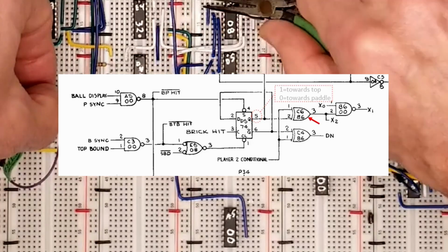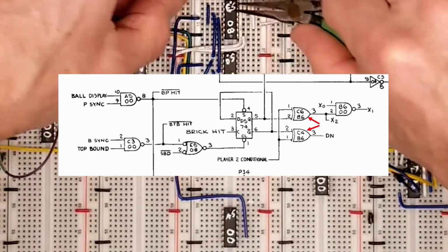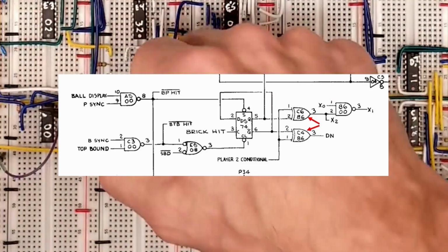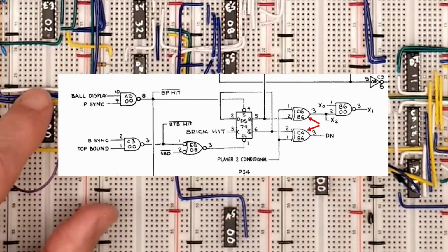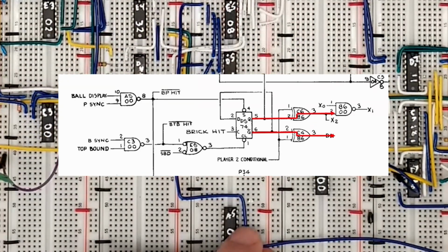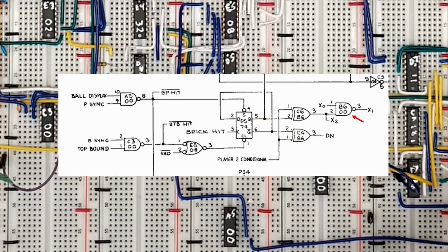These two exclusive OR gates flip the ball direction when player 2 is up on a cocktail table model. When player 2 conditional is off, we can think of these gates as simple pass-throughs. And this other gate helps generate the proper X counter bias values.